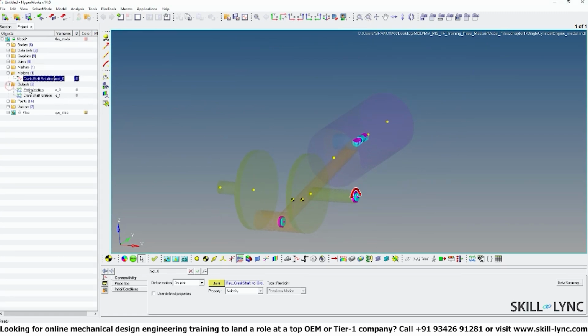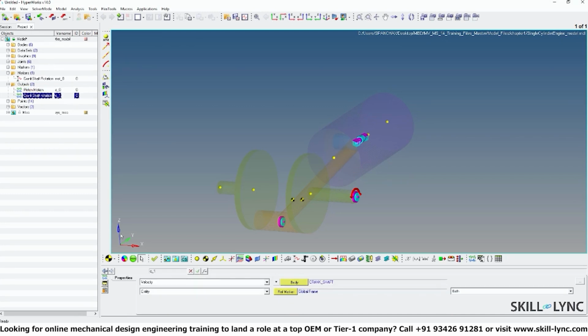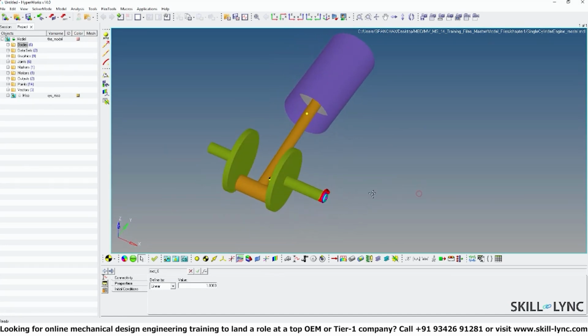And they're requesting two outputs to measure the displacement, to measure the piston motion. So the displacement output, and for the crankshaft rotation we have the velocity output. So we are requesting these two outputs. Okay. So now we've finished exploring the model.